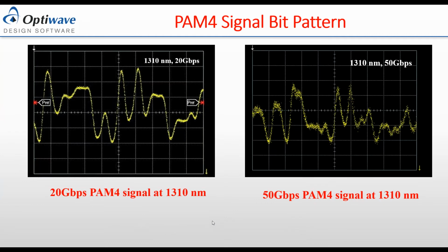And now, in the end, what you need to do is to get your zeros and ones. So if you look at the oscilloscope trace of those levels, you clearly see that there are 0, 1, 2, and 3 levels, or 1, 2, 3, and 4 distinct levels over there, each of them corresponding to 2 bits. So even at 20 gigabits, we have the same thing, and it is almost the same way at 50 gigabits after a distance of 1 kilometer.